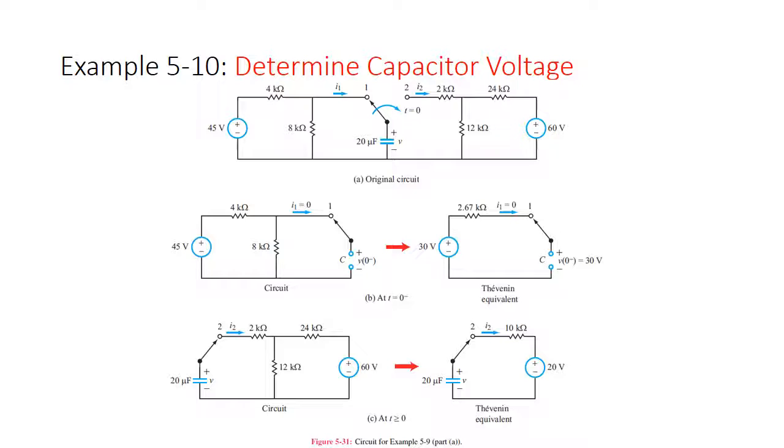Now let's do a Thevenin equivalent for the right half as soon as we switch it. As soon as we switch this circuit, we're going to have a capacitor which is not fully charged, because something is going to happen immediately there, and you are going to have current flowing. We're also going to have 3 resistors there and a voltage source. Those 3 resistors, we're going to work from the right side to simplify those out, given that voltage source. So you can do a source transformation there.